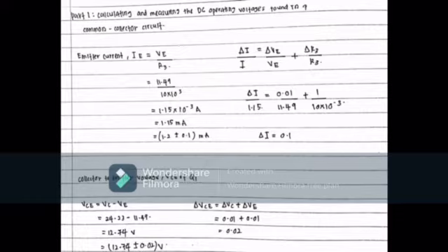Next, we have to calculate the collector to emitter voltage VCE of Q1. VC we get from the DC voltage at the collector of Q1, while VE we get from the DC voltage at the emitter. So the answer of our group is 12.74 volt.